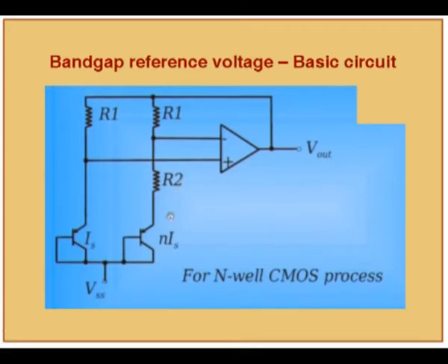And there are many things, I don't want to enter into it, but there are many patents related to this bandgap reference generation, and each one of them claims that now the sensitivity is even less. Because even a bandgap alone may not be able to handle all the accuracy we need, specifically for ADCs. For the design of an ADC, we definitely need a proper way of trimming. Trimming usually is done by laser and it is a costly process after fabrication. But it is required for all types of ADCs.